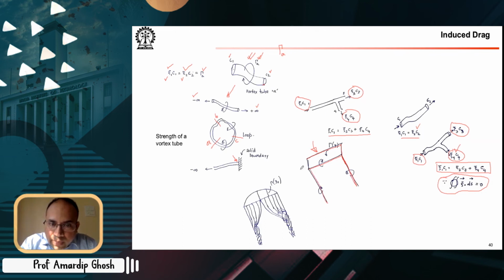On the other hand, in more real settings, your lift at the edges becomes 0 because there is no pressure difference. If lift becomes 0, then circulation at the edges becomes 0, because if you remember, lift is equal to rho infinity u infinity times circulation. So if you think of the lift at various spans, like the span-wise lift distribution, then at the tip chords you have no pressure difference, hence no lift, hence no circulation.